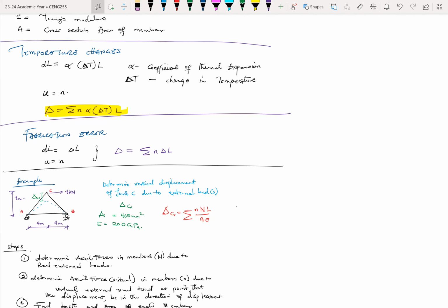We use the method of joints when we are trying to find forces in pretty much all the members of the truss, or a larger portion of the members of the truss, all right? Then we use the method of sections where you're looking at just a few components or a few members. And so depending on what you are looking out for, one method will be suitable or otherwise.